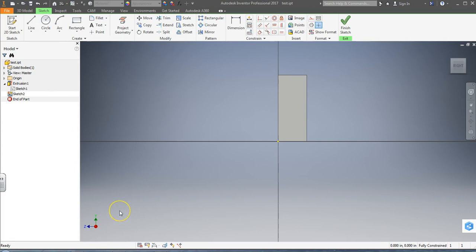If I'm going to do a hole, one of the best things to do is I have two choices. I could make a circle and I could dimension it and put it in a certain spot. And then I could cut it with the extrude or cut. The problem is, if I'm going to do drafting or some of the other operations for toolpaths that I might do, it won't recognize it as anything but a circle. So if I make a point and place it on the surface, we don't know where that is, so you always have to put a dimension.